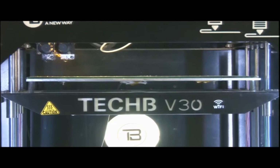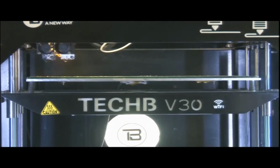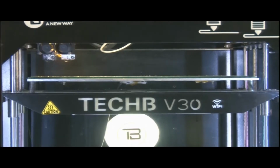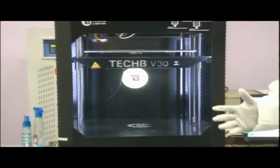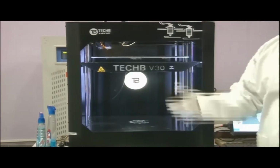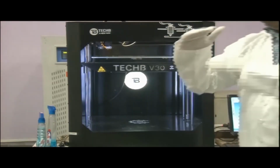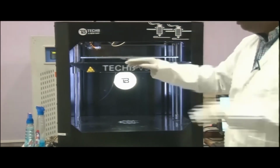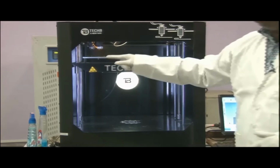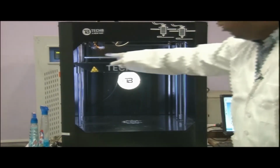In this software, we can set the layer thickness in slicing to 0.1, 0.15 or 0.2, the 3 levels here. Whenever we change this layer height parameter, we need to maintain the gap as well. Say I have fixed 0.15 from the top of the bed to the tip of the nozzle.